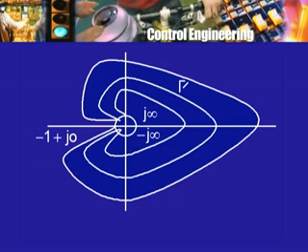So, this is how, with the experimental Nyquist plot, completing it this way by using this mirror image business, and also, if the number of poles is greater than the number of zeros, then this is what is going to be the image of the infinite semicircle. We can look at the relationship of the plot with respect to the point minus 1 plus j 0 and determine the number of encirclements of this point by this plot, and that corresponds to what? By Cauchy's theorem, it equals the number of zeros of 1 plus gh minus the number of poles of 1 plus gh, and that enables us to determine the number of zeros of 1 plus gh in the right half plane.